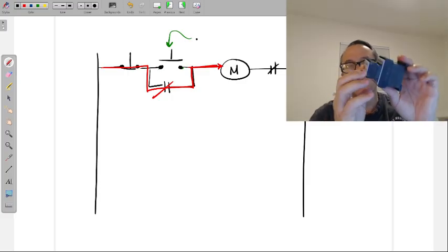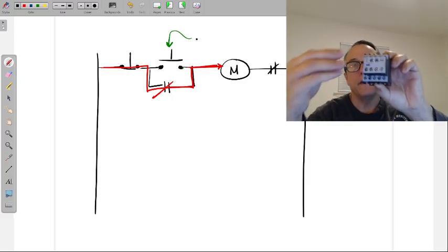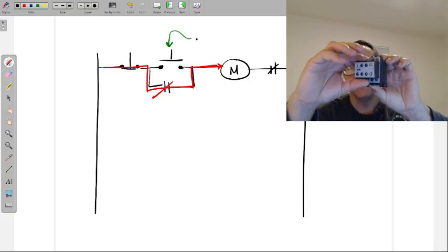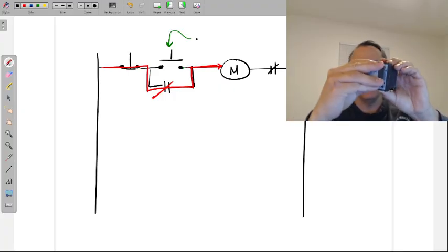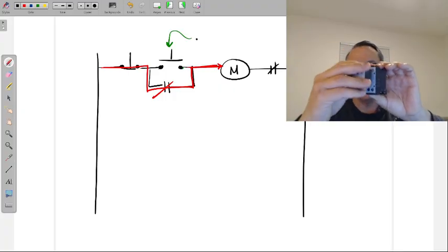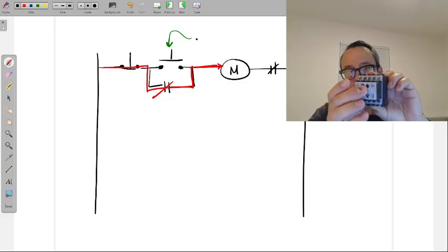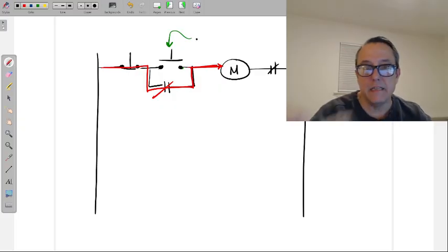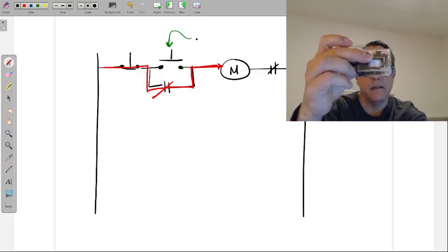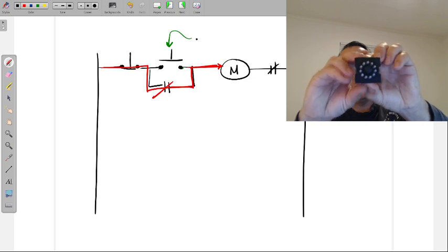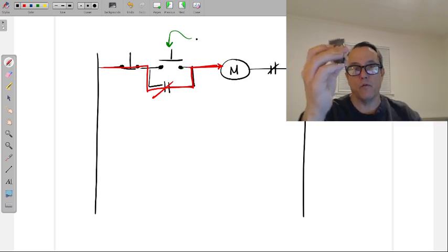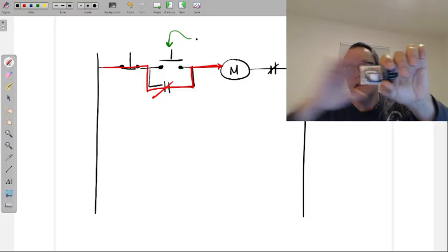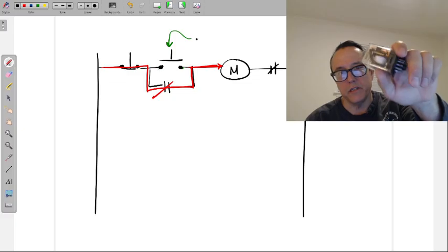If anything happens to the motor starter or anything happens to the auxiliary and I have to replace it, I got to remove a bunch of wires and then take this off and then put the new one in and then attach all of these wires, etc. Just more work extra. Whereas if the relay goes bad, I simply unplug the relay. I just unplug it from where it is, garbage, new one plugged in, control system back on.